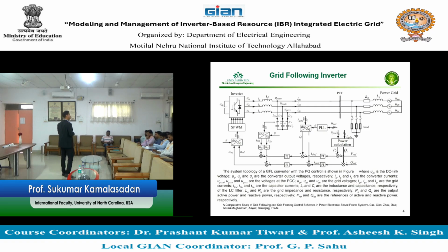So the power error, when I reduce this, I have a problem. How do I reduce this power error? Power is based on current and voltage. Is that power related to current or related to voltage? So you have to first assume that the voltage is not changing and then say that the power is related to current, right? And that reference that you are converting from power to current is through this PI, and you deliver the reference current to the controller from the output of the controller.